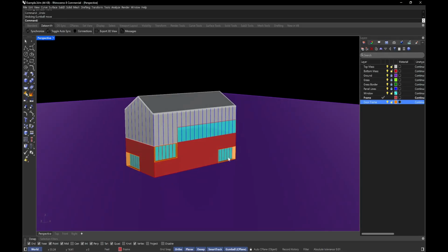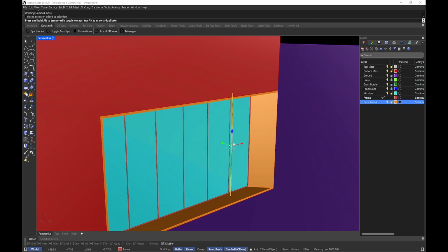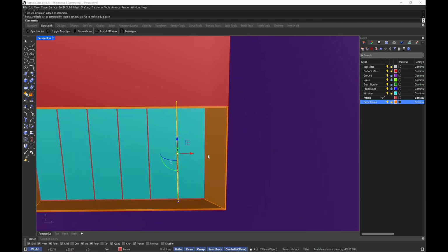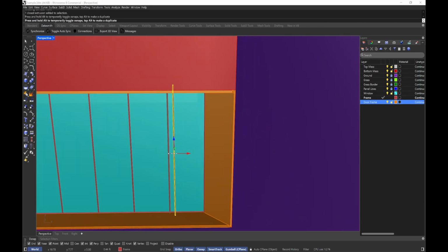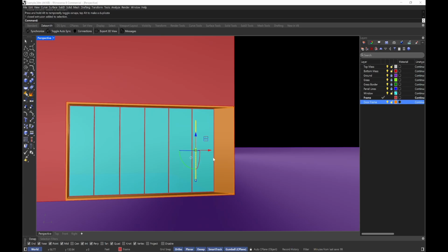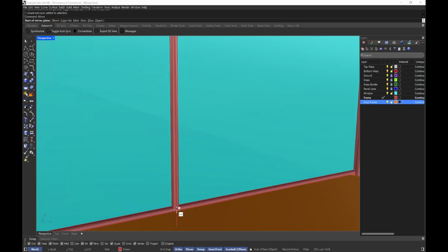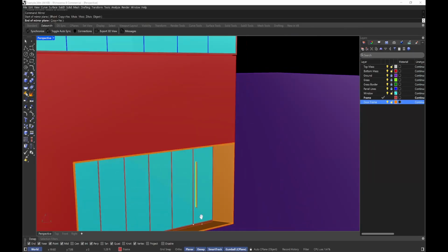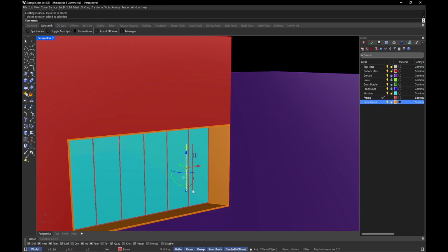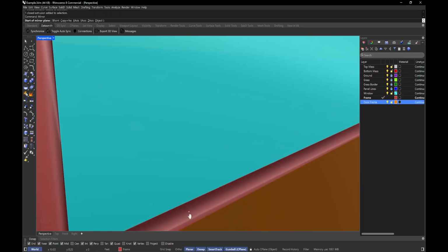Yeah. And so the next thing I want to do is add door handles. So I'll take this here, duplicate it by holding Alt. I'm just gonna eyeball this like that, and then shift it over here like this, and I'll scale it like that. You know, I might make it shorter or longer, but you get the idea. And then I'm gonna mirror like that. Nice. And I'll take this and then I'll mirror it again right here.